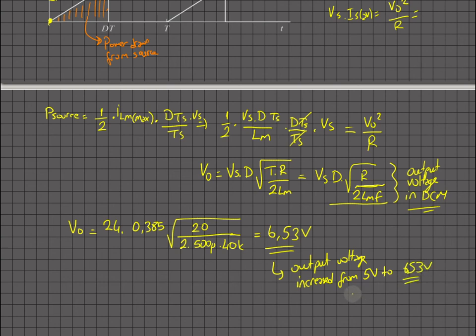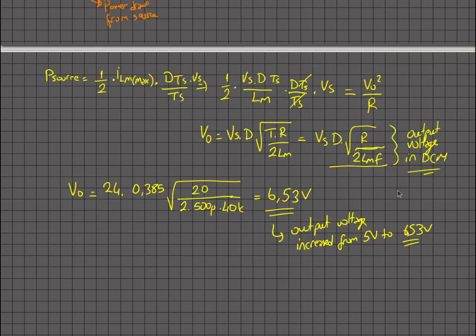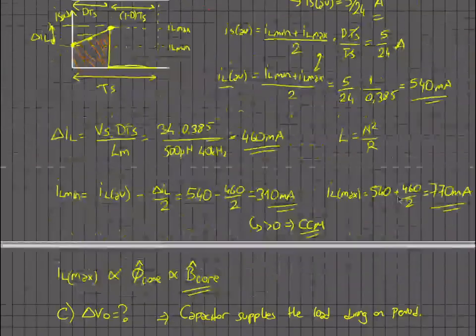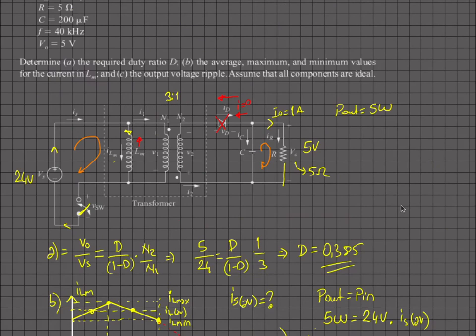We had the same relation in the buck or boost converters. If you keep the duty cycle the same, and the converter gets into discontinuous conduction mode, then you will have some increase in the voltage. So that is what the controllers are for. You need to get some feedback from here, so you will have a controller controlling the duty cycle.